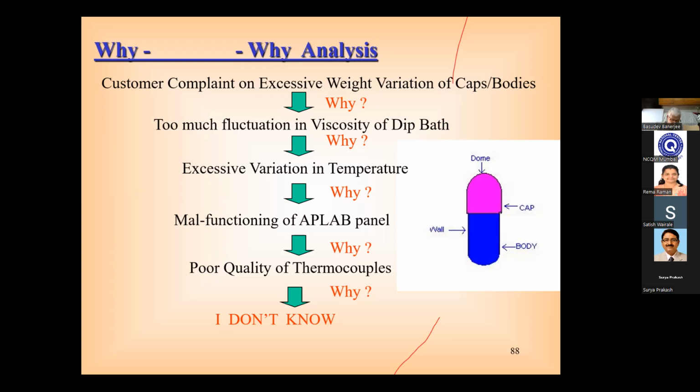You know, my boss was asking, now that you are trained, can you tell me how to go about this one? I said, no problem, we'll go for why analysis of that. Customer complained on excessive weight variation of capsules. Then the boss was accompanying me. I asked why? Too much fluctuation in viscosity of the bath.